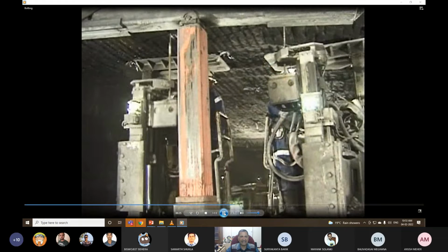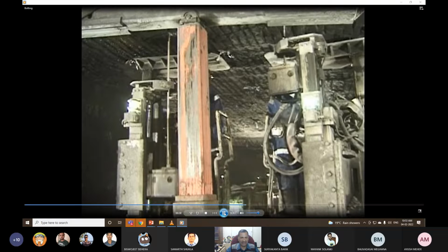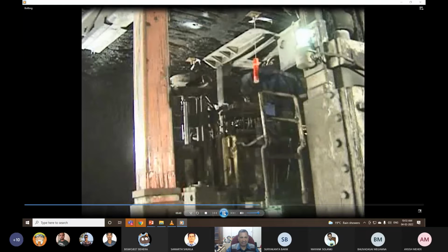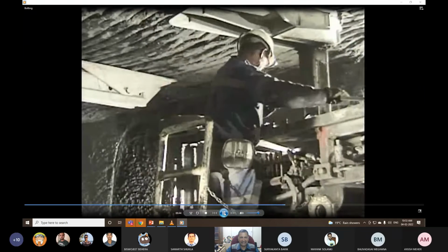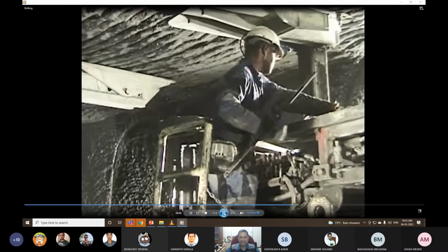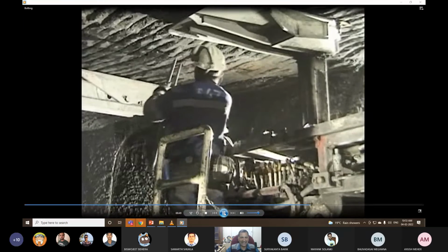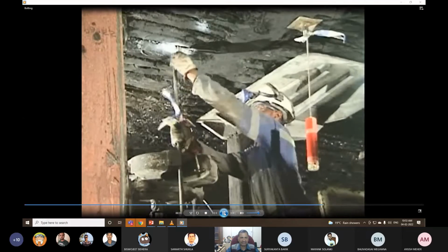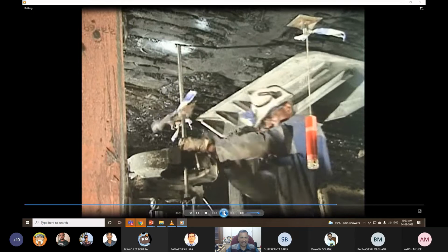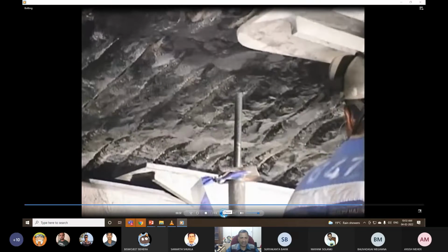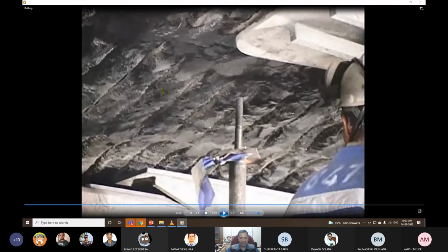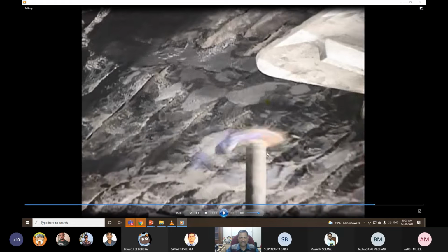When the drilling is over, that rod is taken out, and now the bolting rod is kept inside, and now they are putting the resin capsules inside, and the nut and bolt is also placed into the spanner. Now you see in the spanner that nut and bolt is there with this. Now it is spinning this bolt, right?